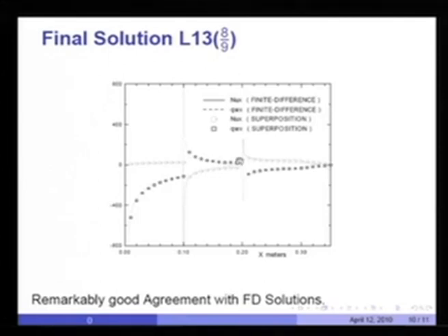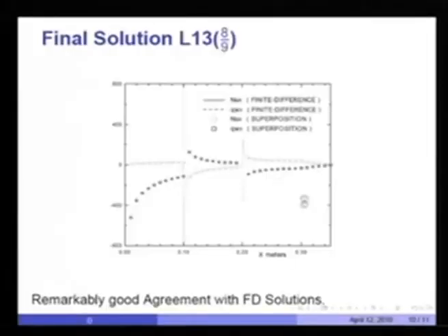And then when you come from 85 to 65, the wall is at 65, but the fluid close to the wall is close to 80 degrees centigrade and is likely to be at a higher temperature than 65 degrees centigrade, and therefore again the heat transfer goes into the fluid, and ultimately up to 3 it is negative, and then it continues when the wall temperature begins to rise, you get positive heat transfer.